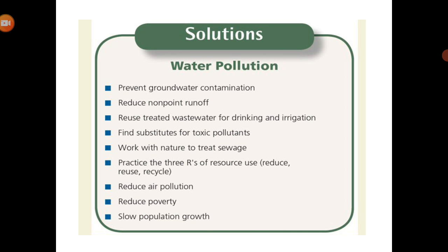In order to treat wastewater, three types of treatment are followed: primary treatment, secondary treatment, and tertiary treatment. Primary treatment is a mechanical process used to filter out solids, gravel and silt from the wastewater. Secondary treatment is a biological process used to remove biodegradable organic waste by aerobic bacteria. It removes up to 90% of oxygen demanding waste by the activated sludge process. Tertiary treatment removes all the remaining pollutants like phosphates and other dissolved inorganic compounds.